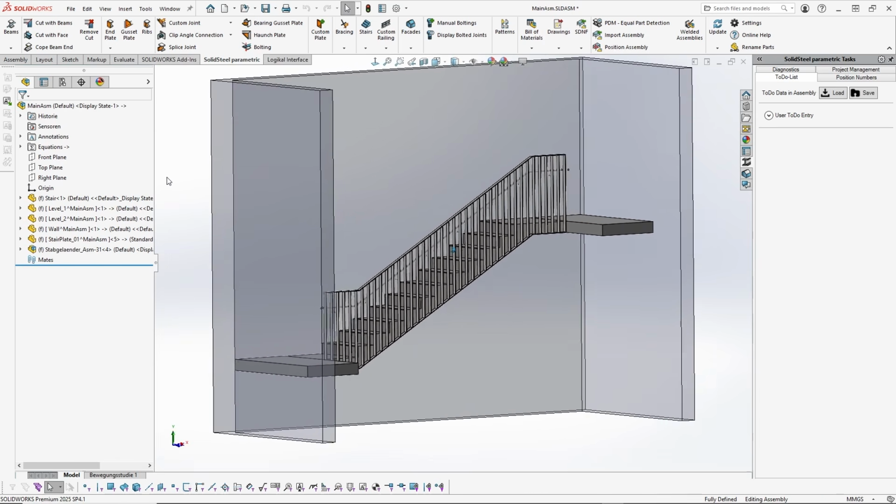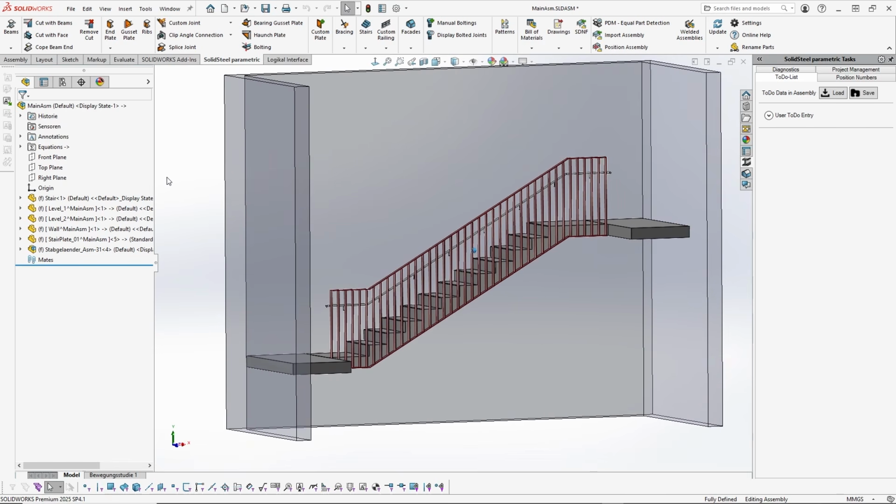The railing we're looking at here will look like this. A vertical bar railing mounted on a sheet metal stringer for concrete stairs. While the vertical bars are mainly a design element, a continuous handrail is not just a matter of appearance. In public and multifamily buildings, it is a requirement. That's why this railing includes a continuous round tube handrail, running at a consistent height and precisely following the stair geometry.